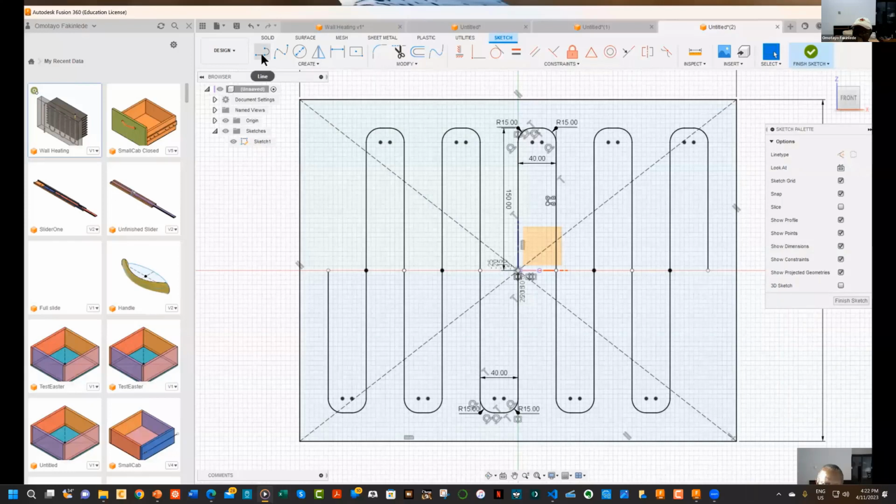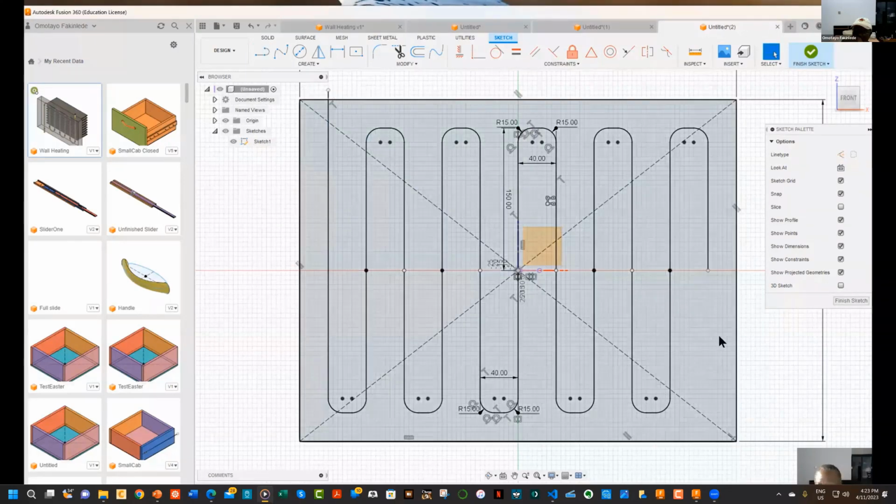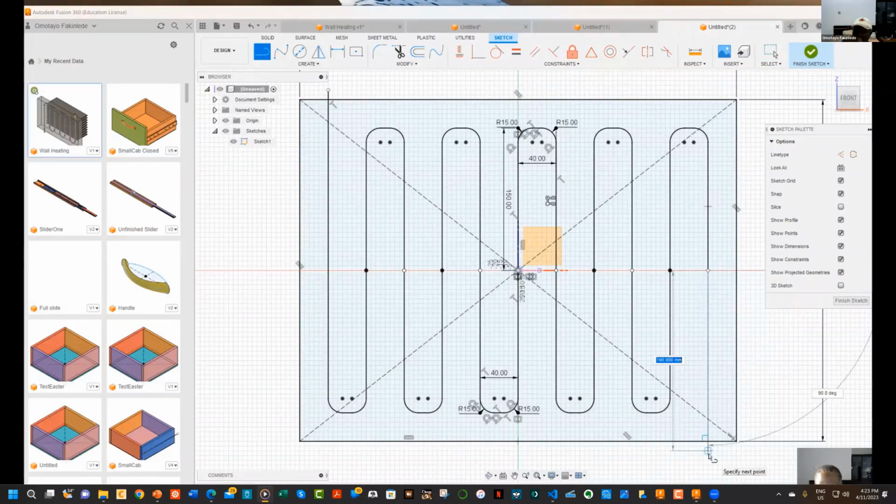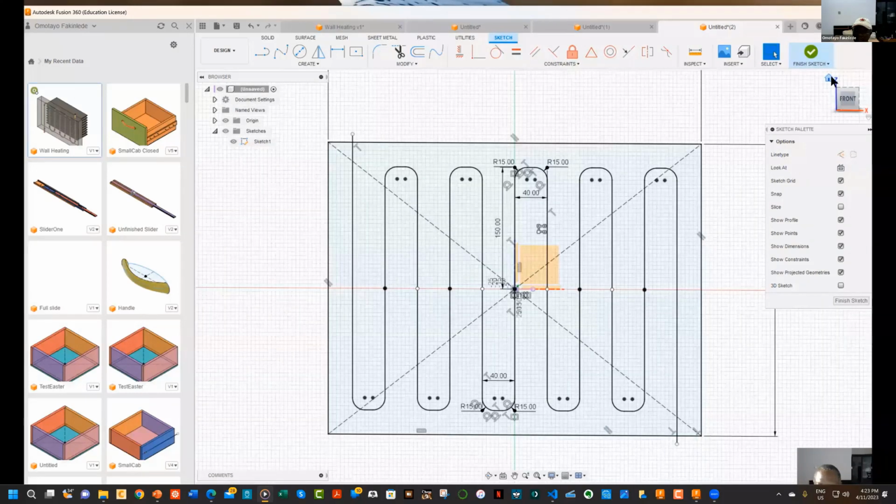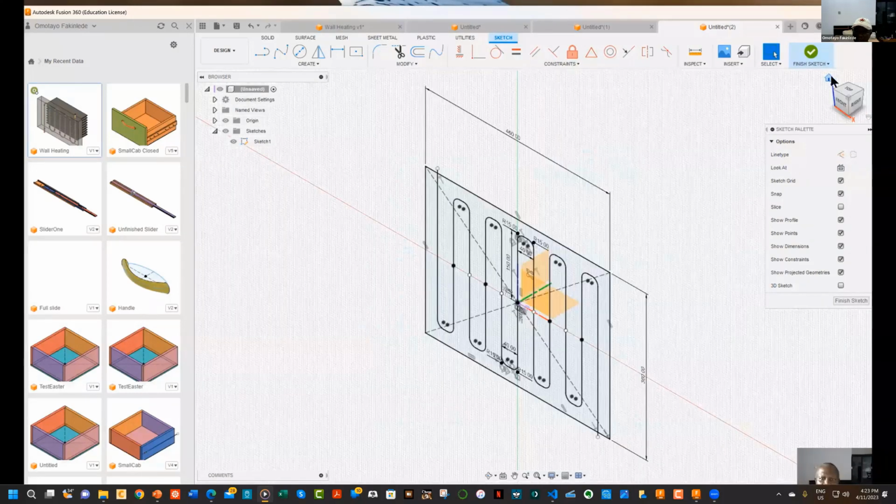The easiest way to do that is just to take a line element, put it here, and stretch it out, and that's okay. Take another one here, a repeat line element, repeat line, using the marking menu, stretch it out, make sure it is vertical, and click escape. So with that, I haven't done that, we're now in a position to create the cutting through where the hole to put the pipe will be. That's the first thing we do.